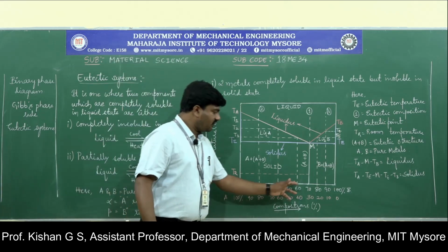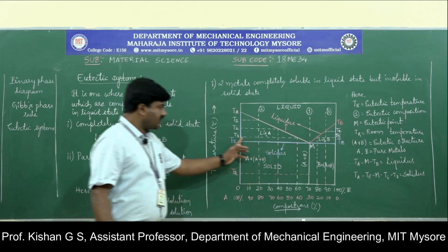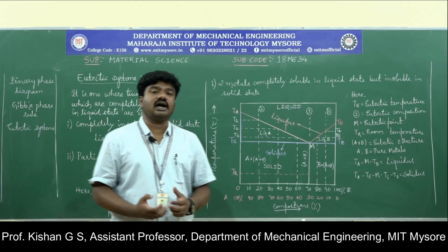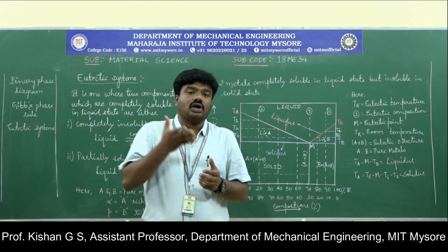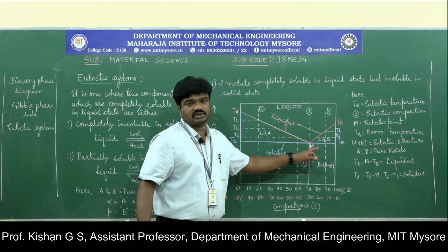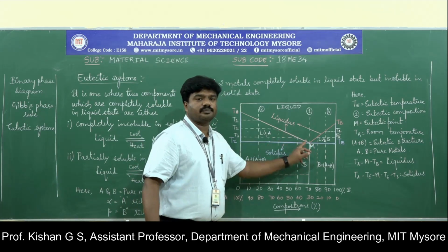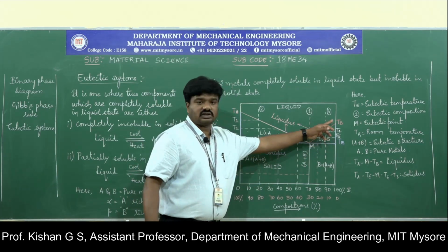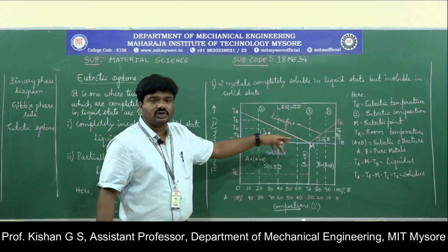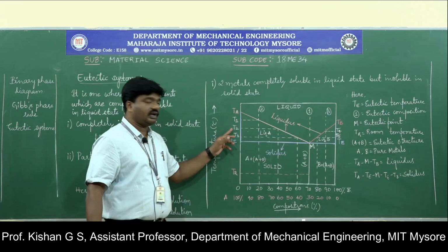So if you draw a vertical to the liquidus line, the temperature is considered to be T3 degrees Celsius, which tells us that the solidification process is almost over, as the temperature is reducing further. At a particular composition M, it is a point where TB, the melting temperature of pure metal B, tends to reduce to form a solid solution. So this is the consideration of T1, T2 and T3.